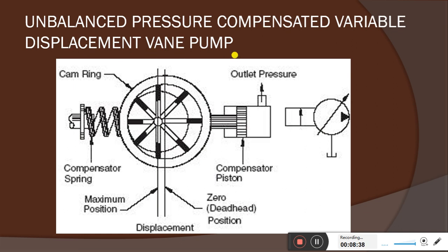While the pumping action takes place, if there is no requirement of fluid in the next stage, for example if you have a still operation, or an operation which should not lead to a higher pressure, the pump experiences higher resistance to fluid flow, and that builds pressure inside the pump.